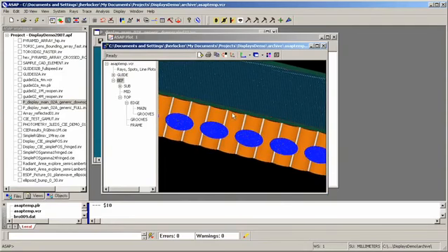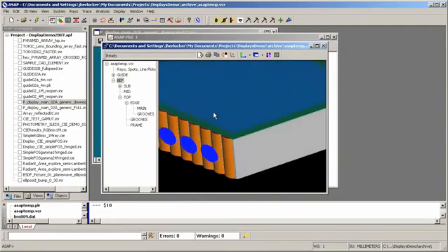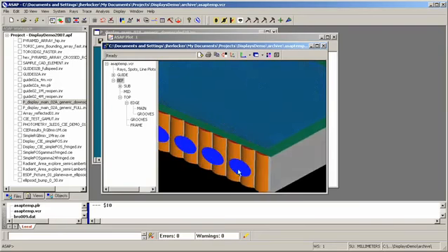What we have here, let's take a look at a corner so that we can really see the structure. Remember, these spots are the spots that show the point of origin or the plane of origin of each of the LEDs that we're using to illuminate the light guide. We have little cylindrical lens structures on the edge that couple the light into the guide.